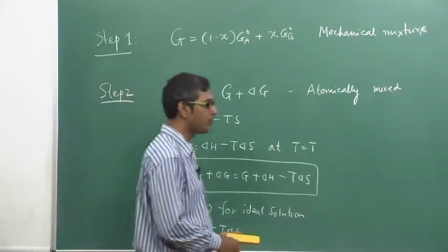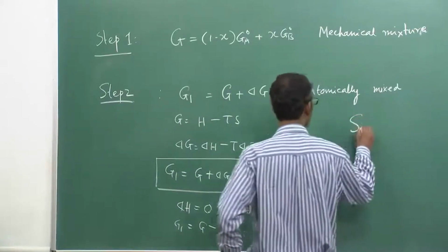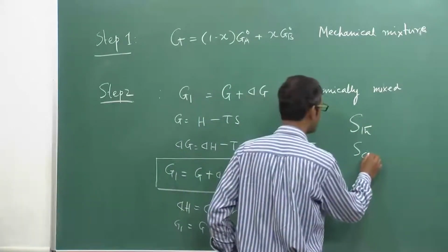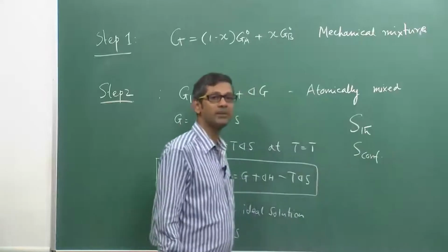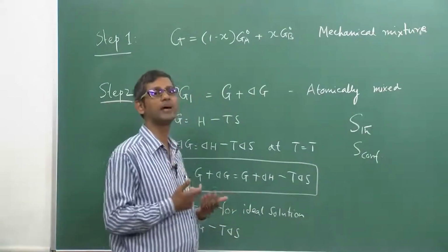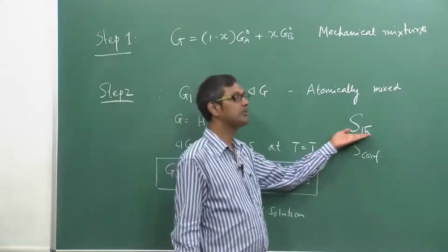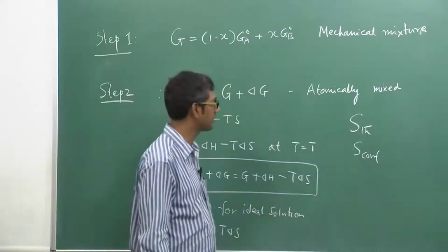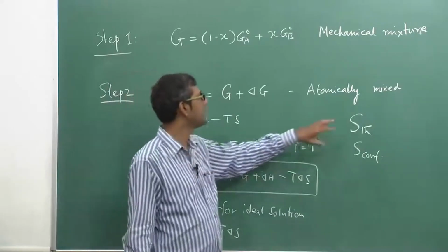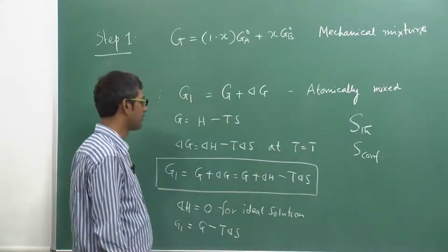Now as you know, entropy has two important parts. One is thermal entropy, or what is known as the vibrational part of entropy, and the other is known as configurational entropy. So what is vibrational entropy? If I heat a system, the atoms start vibrating, so the energy levels of atoms will have different characteristics, and that contributes to entropy because of the thermal aspects. Normally in metallurgical thermodynamics we ignore this part because it is not a substantial amount in case of solutions.